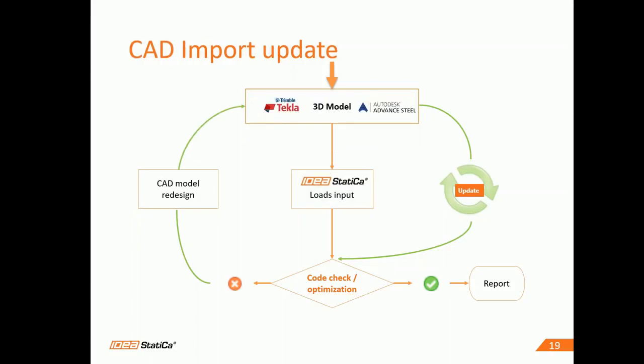In the case of the CAD applications, the workflow is the same. Usually, the engineer starts with the 3D model, and we talk about Tekla or Advance Steel, imports the data to IDEA StatiCa, and performs the input of the load effects manually. Then the code check can be done.